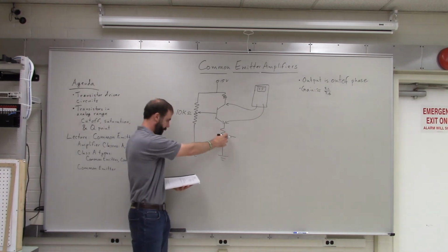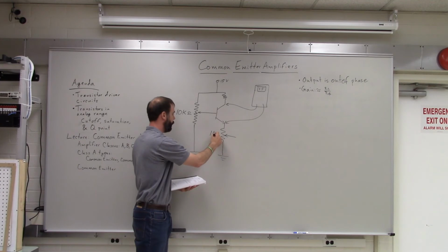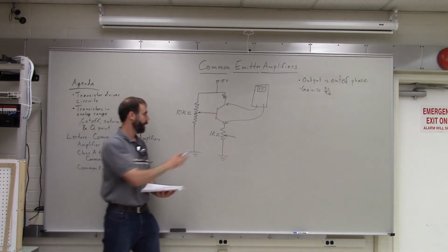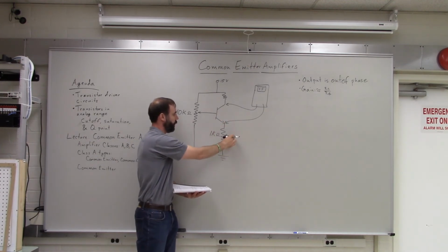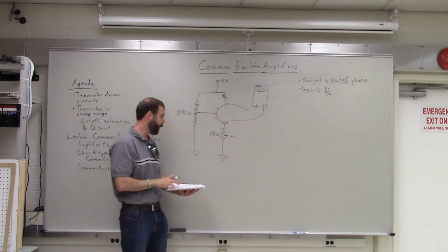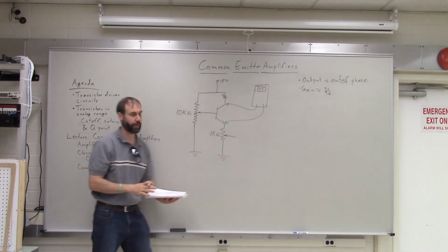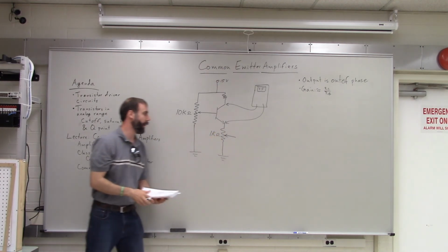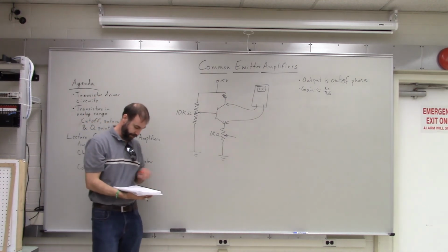You'll notice that this resistor down here is also a potentiometer. All right? For this first part of the circuit, you're only going to use the two ends, and you're going to leave the middle loose, not connected to anything. Later on, we'll connect this over to the swamping capacitor, but that's not until later, all right? But you need to put the potentiometer in there now so that it's there when you need it, all right? So that's the first part.